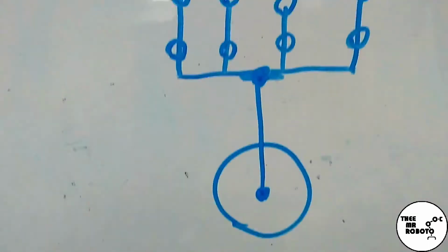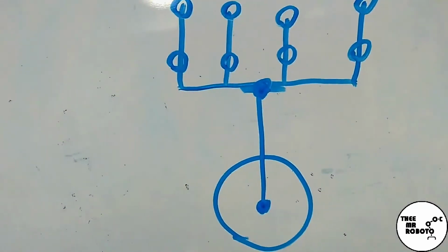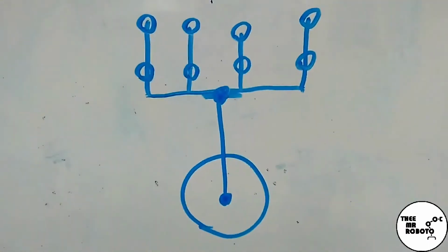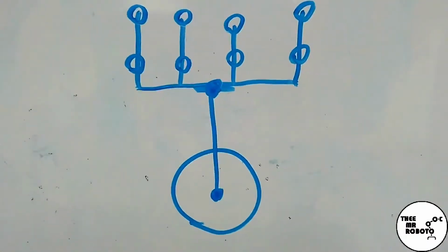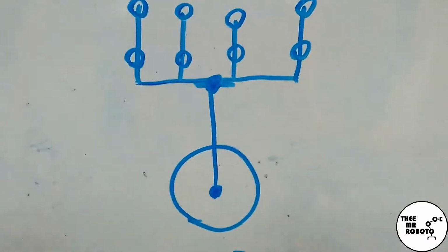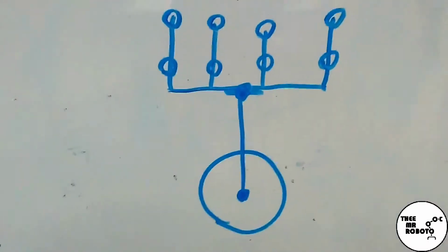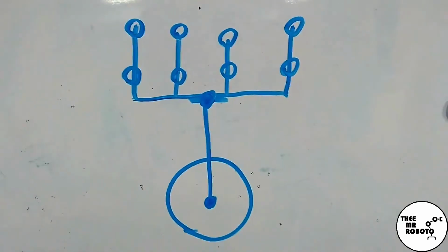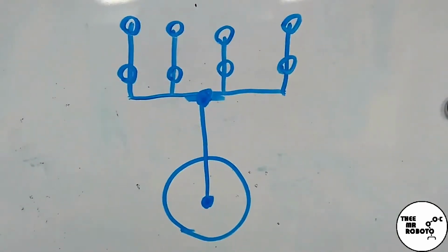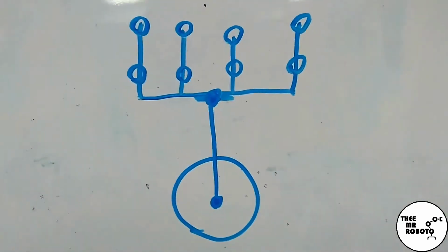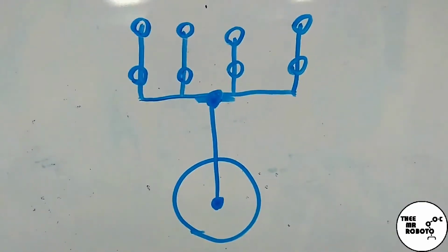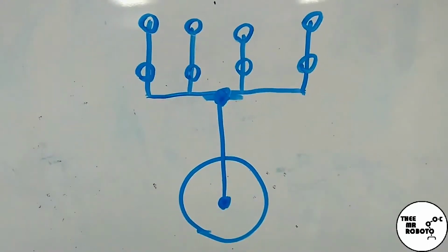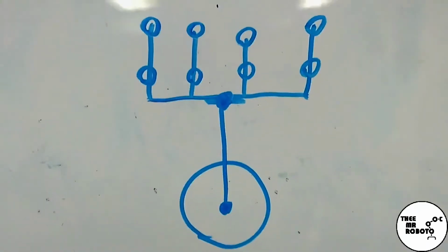Okay, so you could program your robot's motions to use only these two coordinate systems, and your robot would work. Okay, the path would function like it should and everything, but it wouldn't necessarily be the best process or the best programming procedure for your process.